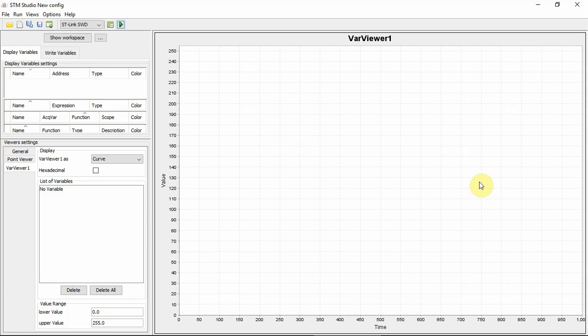In this episode, I'll show how to use the STM Studio. The software that was developed by ST helps to debug and diagnose STM32 applications while they are running, by reading and displaying their variables in real time. The STM Studio interfaces with the STM32 MCU via the ST-Link development tools. This software can read the registers of the application without stopping the program.